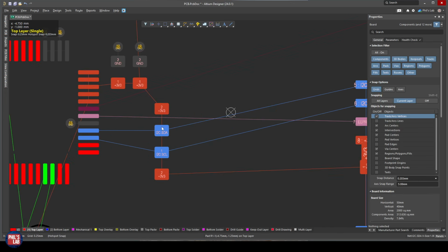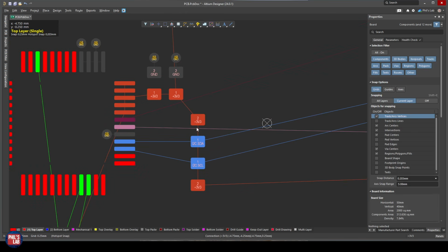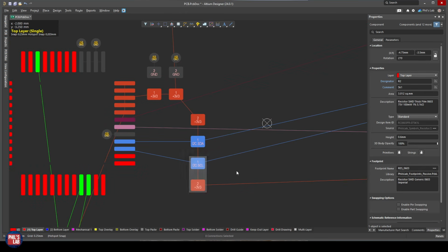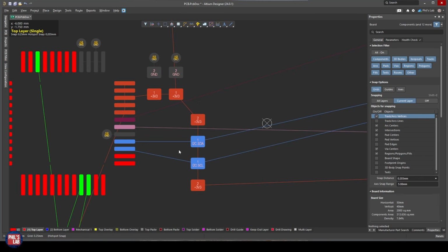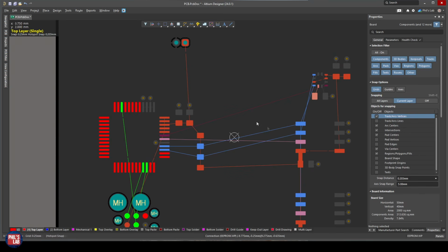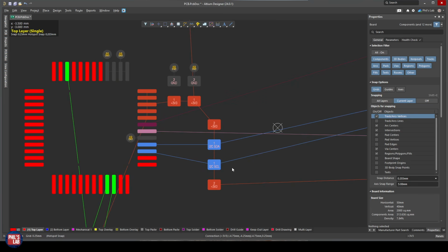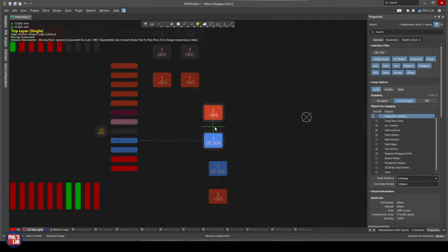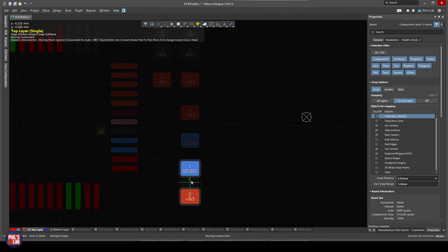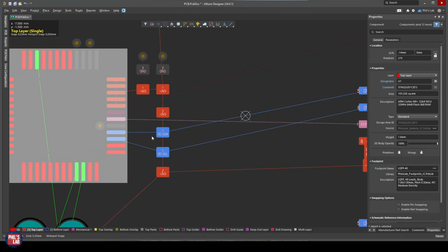The first thing I typically do might be to somewhat roughly place the location of my pull-up resistors. You can see here, I've got these two 5.1K pull-up resistors in this example. Again, it depends on the speeds and what we talked about near the start of this video. Typically, you might want to place them centrally to all of these devices, but oftentimes the actual location doesn't really matter too much. I prefer to put it close to, for example, the host controller, so in this case, the MCU.